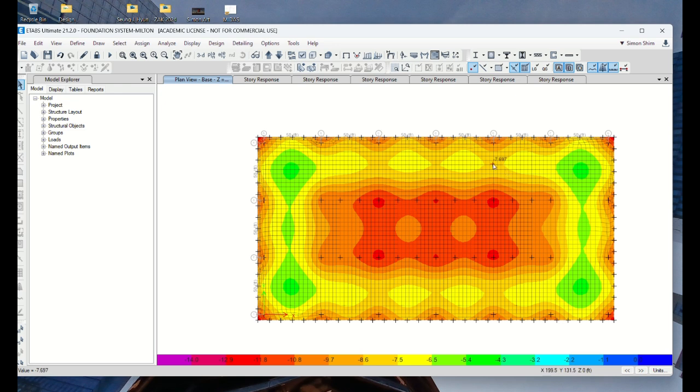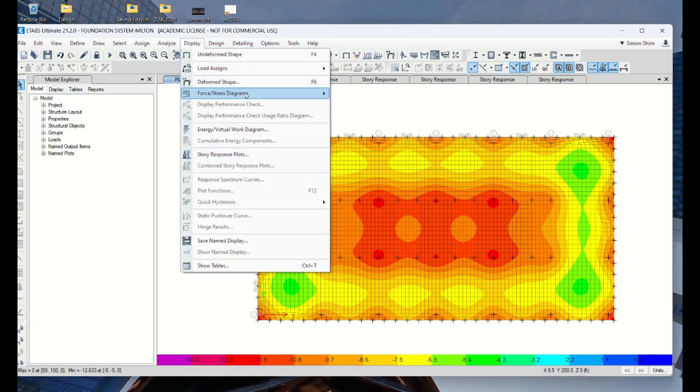So overall, the tower superstructure loads come down, especially the majority of dead load comes from the wall. So you're gonna see more intense soil bearing reaction because more loading is coming from the wall. But outside column loading is relatively small, so you're gonna expect soil bearing stress like this, right? Okay, it looks fine.